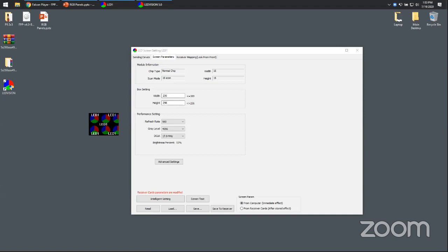Why not run Colorlight with a BBB? Why only on a Pi? Well, the easiest way to say that is the Pi has a gigabit adapter nowadays. The BeagleBone Black does not. There's that issue. You would have to go out to separate hardware. But we've seen it where it staggers and can't keep up, and it creates artifacting on the Colorlight card. So it's typically just not recommended to use a BeagleBone.